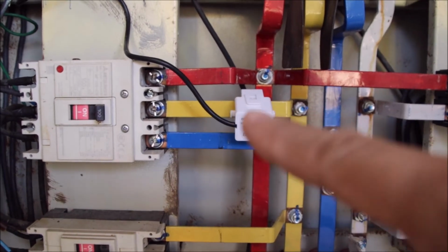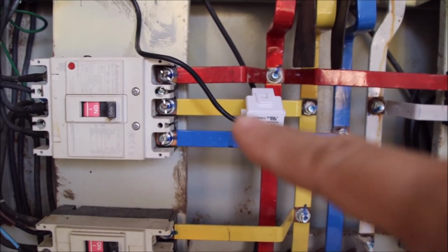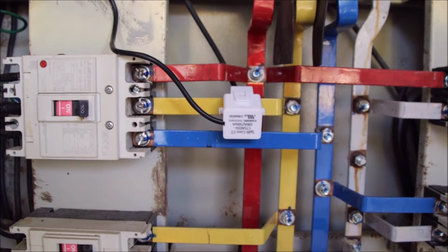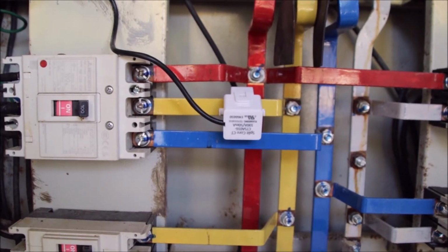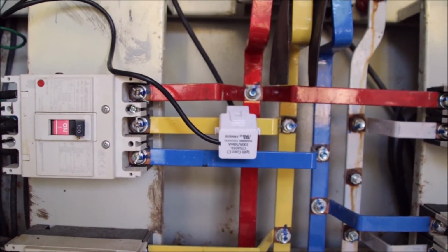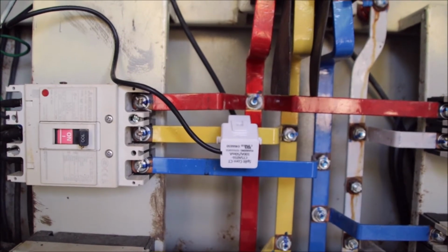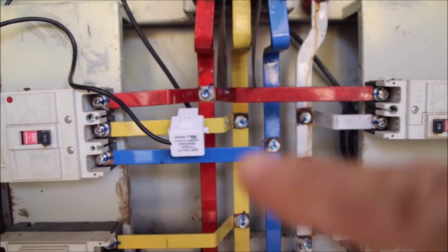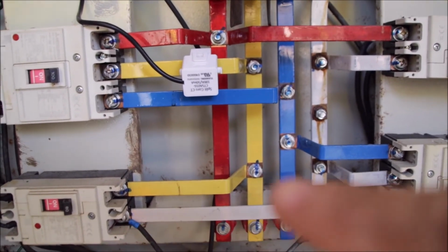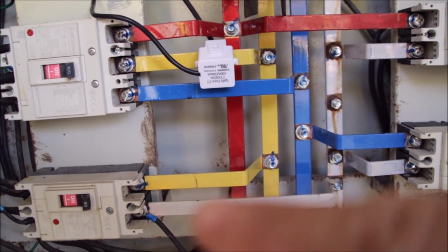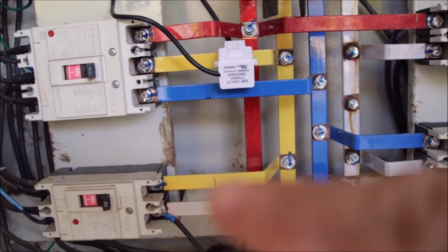And this bus bar is a 15mm wide copper bus bar. The original CT is a CTSA 016, that's the name of it, and the 16 especially, that number stands for a 16mm hole. So 15mm bus bar, 16mm hole on the CT, fits right well. But the problem now, you see, I want to discharge into the yellow phase here, the phase number 2, and also kind of utilize this one lane. This goes to 3 bungalows.